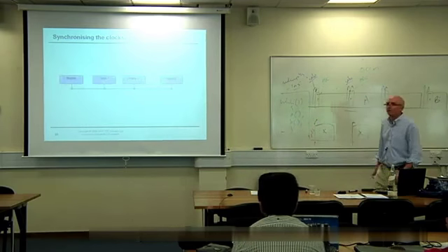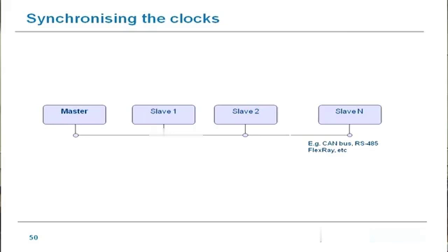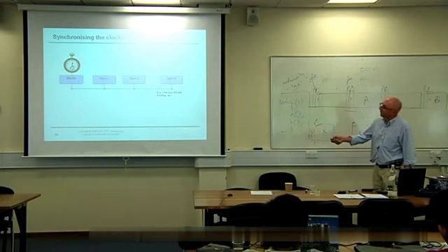This is the most important slide in this session. We're going to take a set of nodes. We're going to hook them together on a bus. Some of you have seen some of this before, and you're back in familiar territory again. On the master node, we're going to drive the scheduler in just what we've done before. So we've got our timer driving the scheduler, generating periodic ticks, driving the scheduler on the master node. One interrupt per microcontroller.